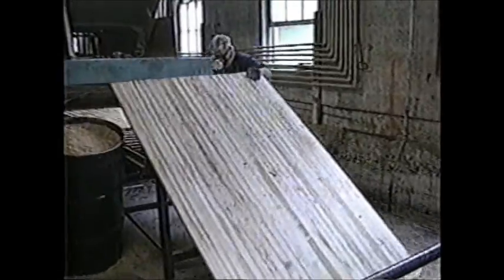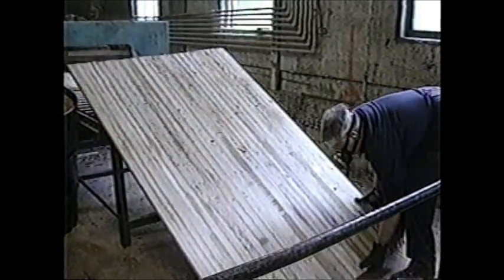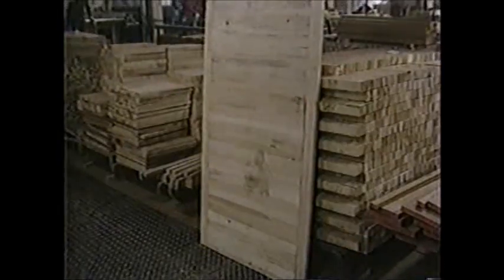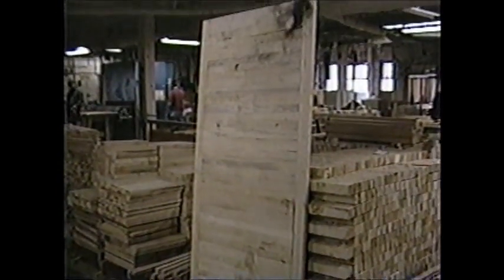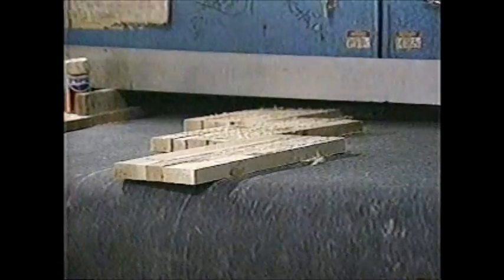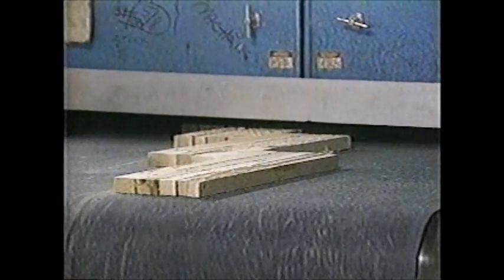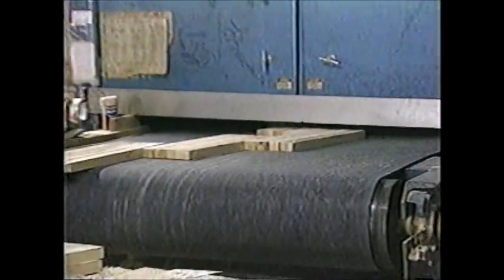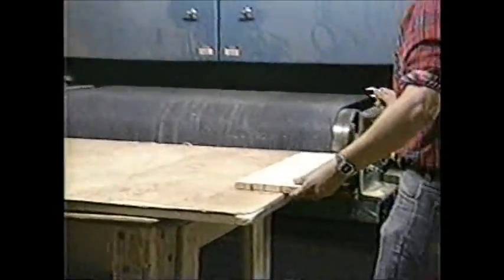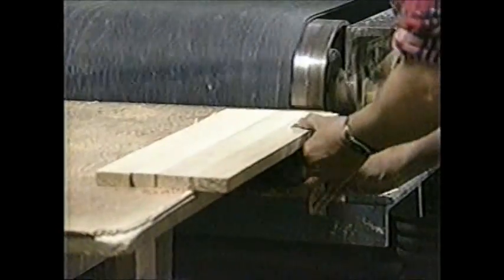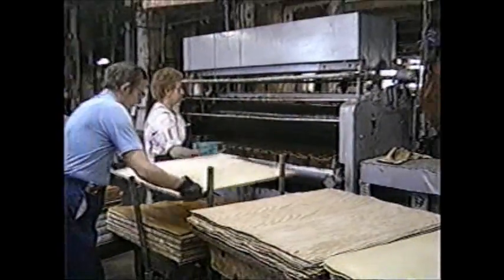When the lumber core emerges from the RF press, the strips are joined, but the panel will be put through an abrasive planer to remove glue extrusions and to obtain a satisfactory surface for veneering. This damaged panel had excessive moisture content in a damaged piece, which created a hot spot in the radio frequency press. The abrasive planer reduces panels to a specified thickness, removes glue extrusions, and ensures a satisfactory surface for the application of veneer.